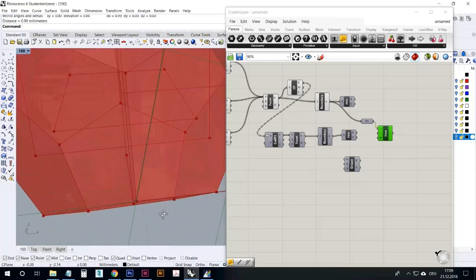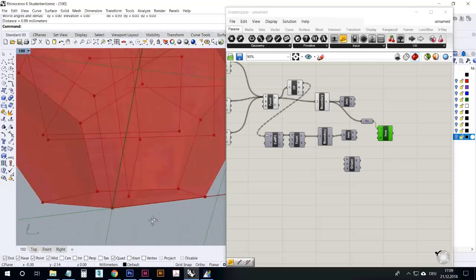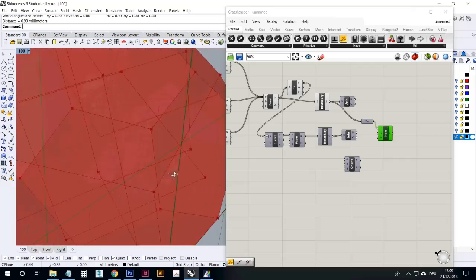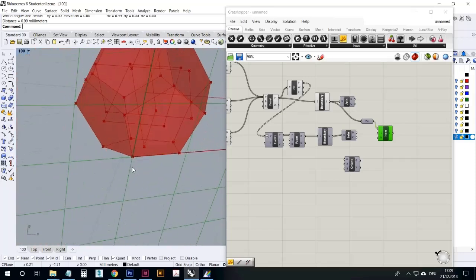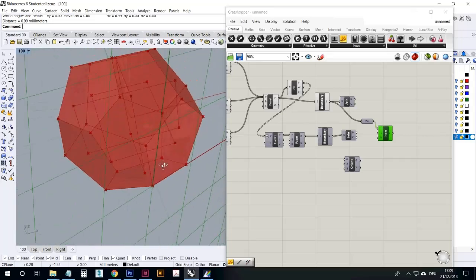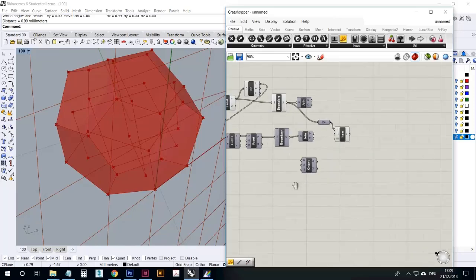It uses one of the corner points for its origin, or its center point. It's 0, 0, 0, which is not really so good if we start to draw something in the middle of another plane, which is recommendable to know where things are. We need to have this in the very middle of this pentagon. So we can actually reposition the plane so that it lands on the pentagon, and I'll show you how to do that.